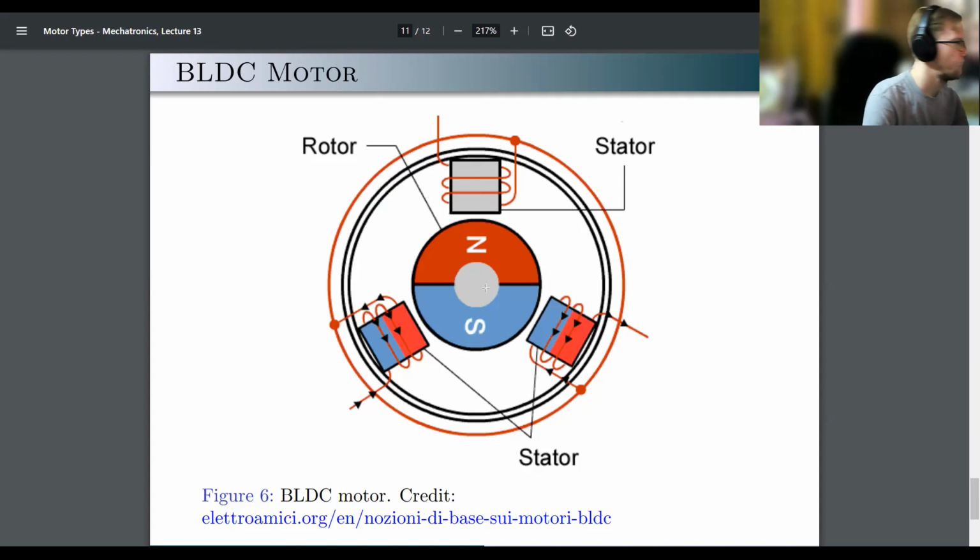Now, for walking robots, this is used without thinking about three phases. So I've seen people using those motors. They don't think about three phases. In a way, all of this can be abstracted away if you do it as a servo motor. So if you create a control loop, which will generate your desired torque, while everything else is handled inside the loop. That is a very typical approach.